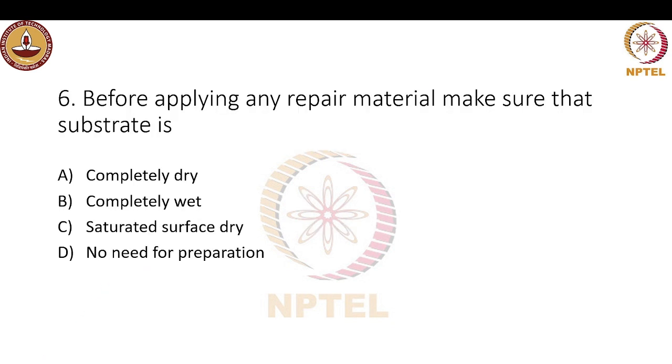Actually, in industries, whenever we are doing flooring, we'll have a requirement of using the floor immediately. So at that time, we just spray this compound. It is like polyamides. We just spray it on top of the surface, and it prevents any sort of evaporation that is bound to happen. In that way it will do the curing. That is a curing compound. Polyamides is a chemical. Okay, thank you.